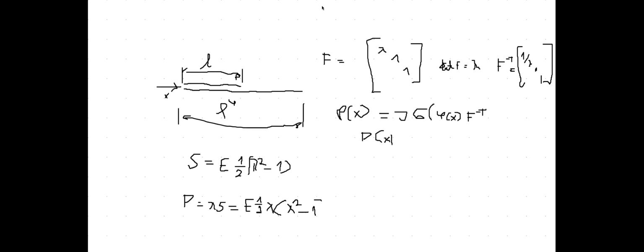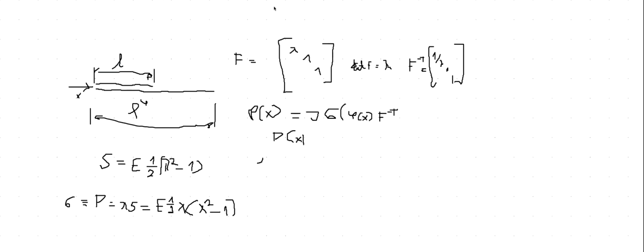So now I go into these limit cases, and that becomes the same value as the true Cauchy stress, because this is really the judge of the real physical behavior of the material. You cannot judge what is going to happen in terms of plasticity or other things by looking at these different pictures of the stress. You have to go to the really physical stresses, the ones that are really acting in your deformed body, in order to get the proper impression of what behavior you can have in this particular case.